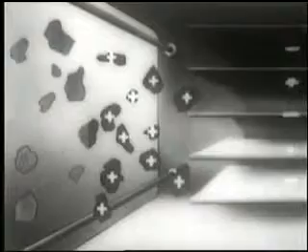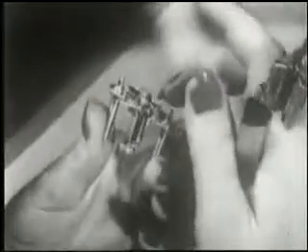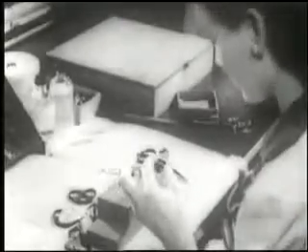As incoming air passes through the field of these wires, each particle of dirt receives a positive electrostatic charge. When the positively charged particle reaches the collector chamber, it's attracted to and deposited on negative plates. In this way, air is cleaned so thoroughly that dirt particles down to a quarter millionth of an inch are removed. This is a vital advantage today, not only in homes and public buildings, but in industrial plants of all kinds. For instance, in plants manufacturing delicate instruments, where air cleanliness is necessary for precision work. In workrooms where optical systems are assembled for a host of military purposes. In inspection rooms where minute parts must be closely examined under high magnification.